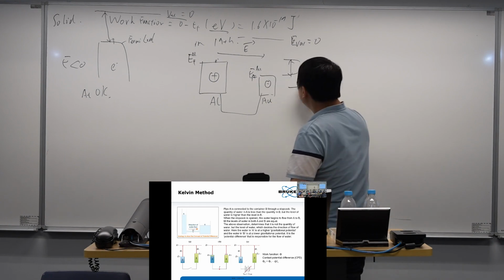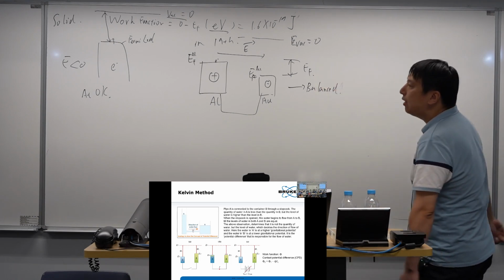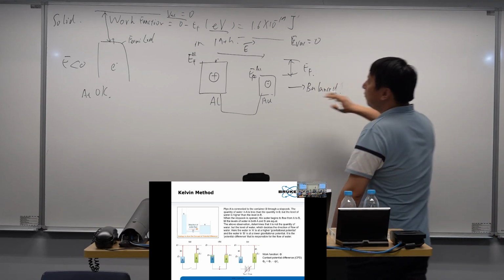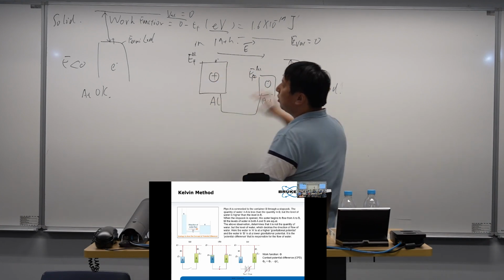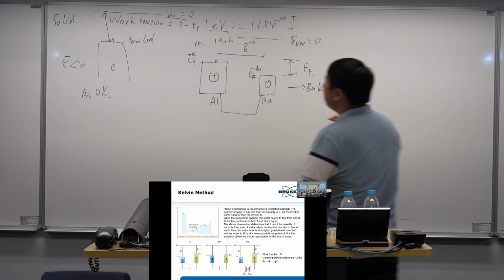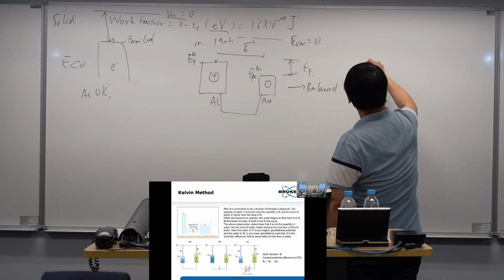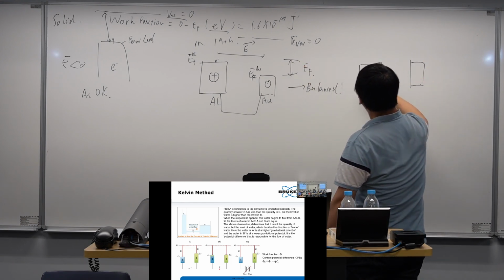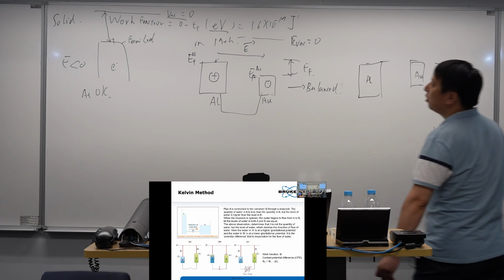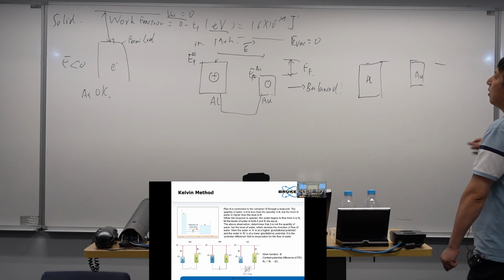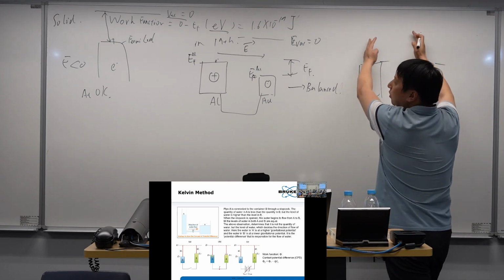Okay, this electric field will prevent the electrons from going on. And when it reaches balance, we know the Fermi level on these two will be the same. So the electrons will not continuously move on, but as a result, we actually establish an electric field.